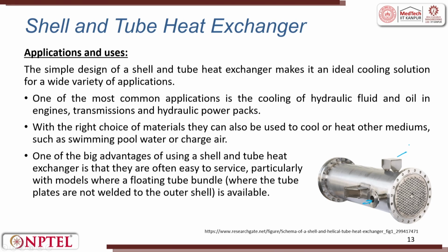The simple design of shell and tube exchanger makes it an ideal cooling solution for a wide variety of applications. One of the most common applications is the cooling of hydraulic fluid and oil in the engine, transmission and hydraulic power packs; wherever they use this shell and tube type heat exchanger. With the right choice of material, they can be used to cool or heat a medium such as swimming pool water or charge air. So, you can try to do anything.